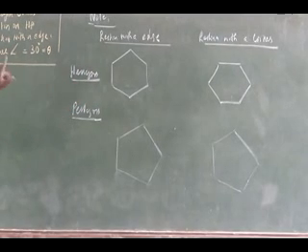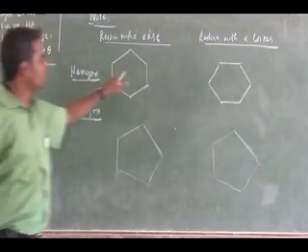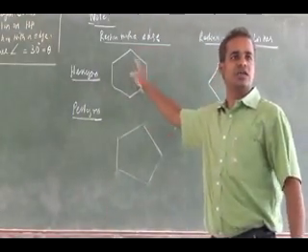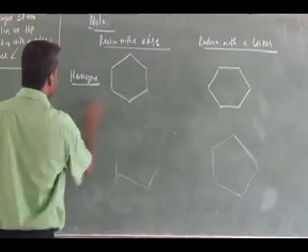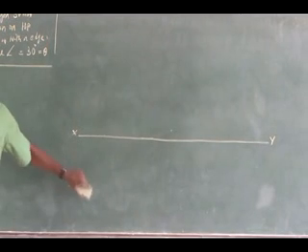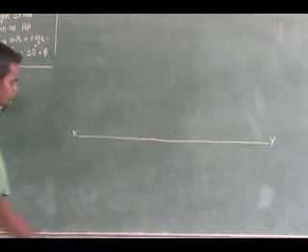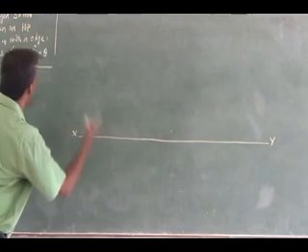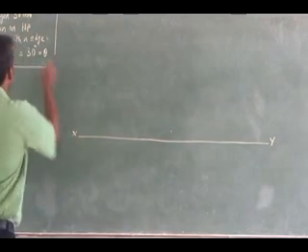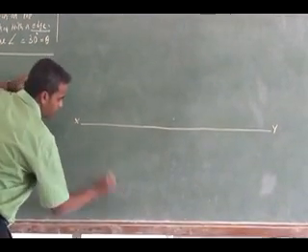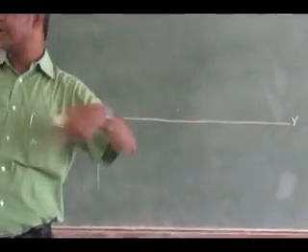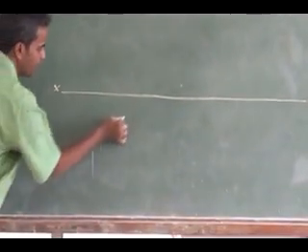So now, make a note in your notebook. Very essential, right? Now, as per the problem, how is it resting? With an edge. So I can draw the hexagon in this orientation, with the edge kept vertical. In this orientation I can draw my true shape. So where do I have to draw the true shape? On the plane from which it is inclined, it is going to be parallel to that, so the horizontal plane. It is a hexagon, so I have to draw a circle and inside it draw the hexagon. Quickly I have to draw that.